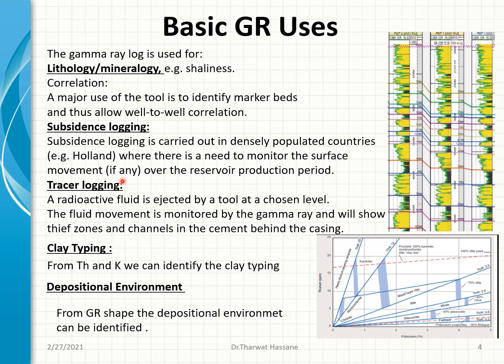Also, sometimes use it for subsidence logging. That means in Holland, for example, they use a gamma ray to see the movement of the surfaces by logging before and after, and the difference between them. You can see how much the subsidence depth has shifted during the movement in the sea like that.